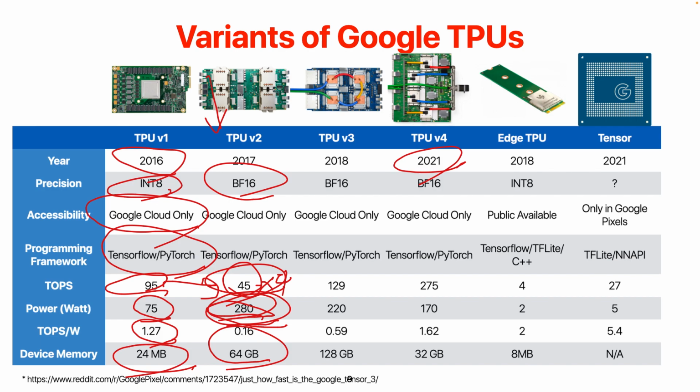And there is a reason for that, because for the first version of the TPU, they use integer data and they only store quantized data. And the matrix size they are dealing with is only 256 by 256. So 24 is good enough. However, here we are dealing with BF16, and the accumulation is actually in 32-bit. So you actually want a lot larger memory space for that.